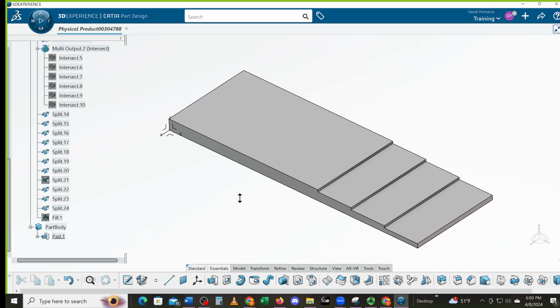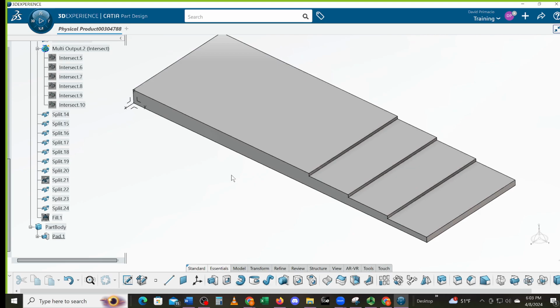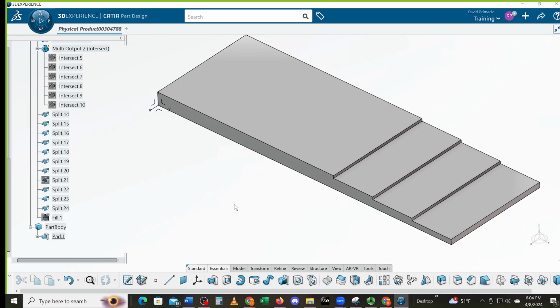So with the wireframe, I came in and did a cut on those steps. I created a solid, trimmed them, and then joined them all together so that they all reflect any type of change in the planes. So that worked. You joined the profile? Yep, that should work. And then when you go to make your face, you just pick the join only. Yep, I picked the join on the steps and everything else, and it's perfect. That's great.